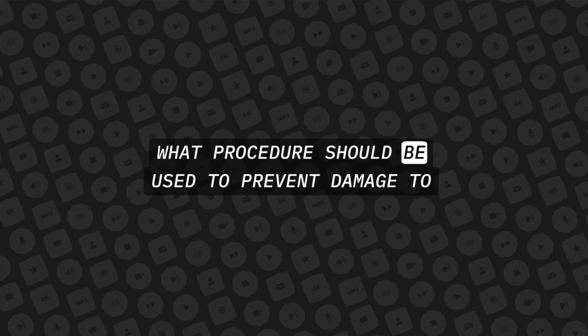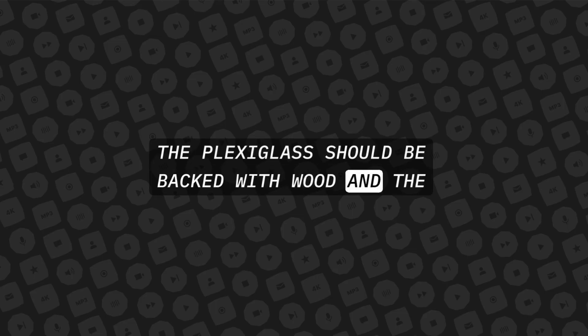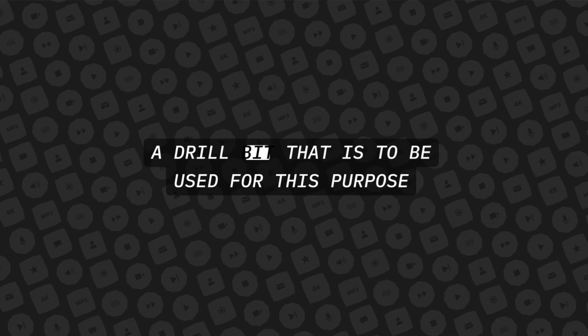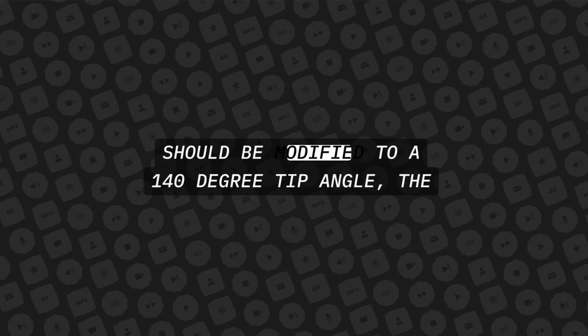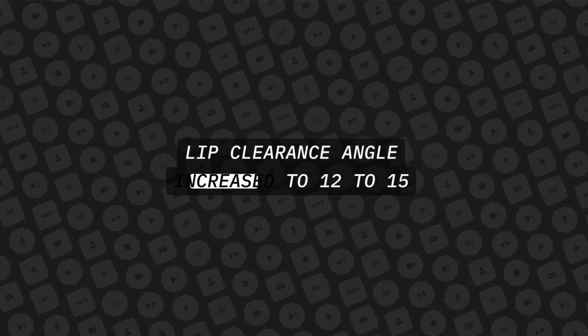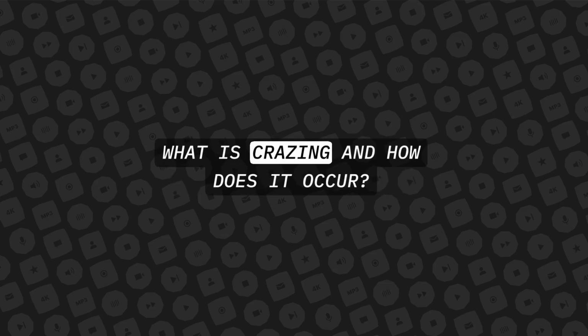What procedures should be used to prevent damage to the hull when drilling through plexiglass? The plexiglass should be backed with wood, and the feed slowed as the drill point breaks through the underside of the sheet. A drill bit that is to be used for this purpose should be modified to a 140-degree tip angle, the cutting edge to a 0 rake angle, and the back lip clearance angle increased to 12 to 15 degrees. What is crazing and how does it occur?